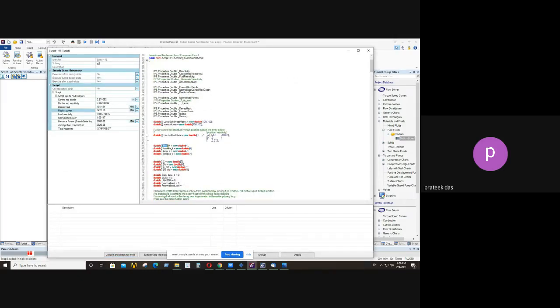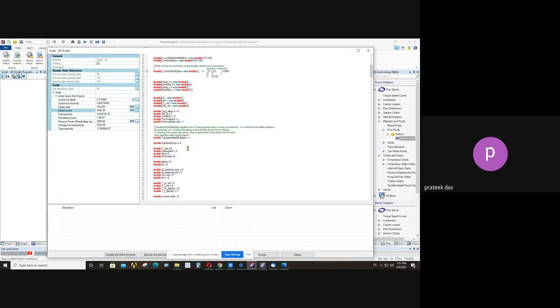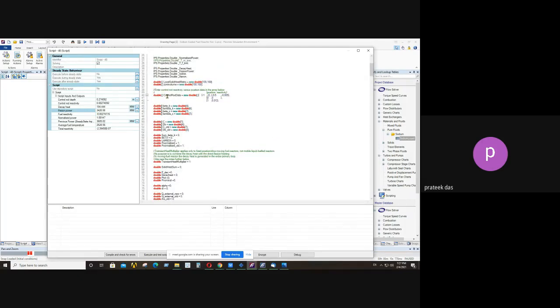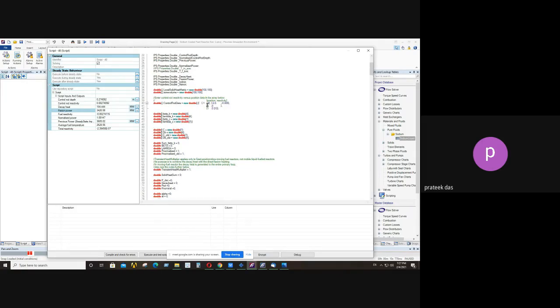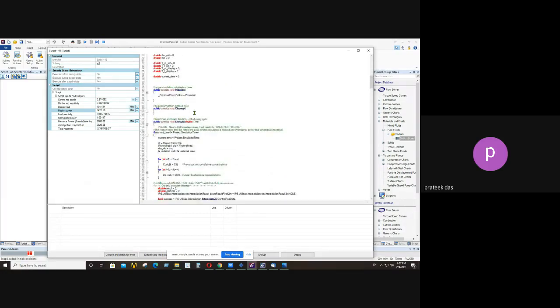In this case we have specified different constants for the rate of reactions. Then you will get different time dependent values, so you can link it to the solver time. Then you can specify the control rod data. In this case, it can act as a matrix format, in which whenever you get data, it will plot those into Cartesian coordinate format, and according to that, your control rod movement will be maintained.